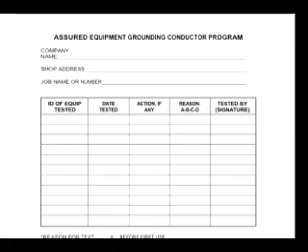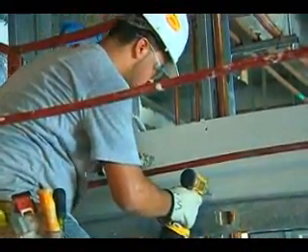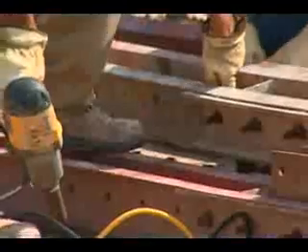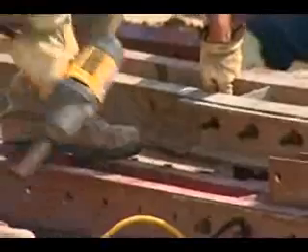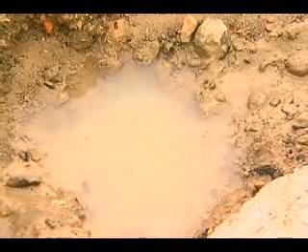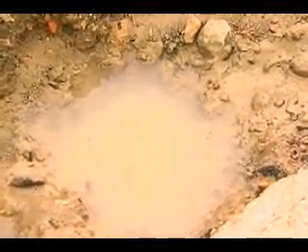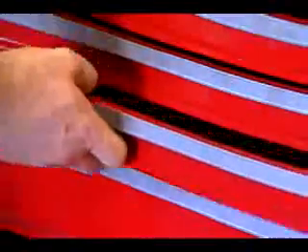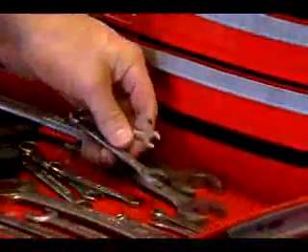Tools should always be used within their design limitations. Misuse can cause injuries. Use gloves and appropriate safety footwear when using electric tools. Never use an electric tool in a damp or wet location. Keep work areas well lit. And finally, store tools properly in a dry location when not being used.